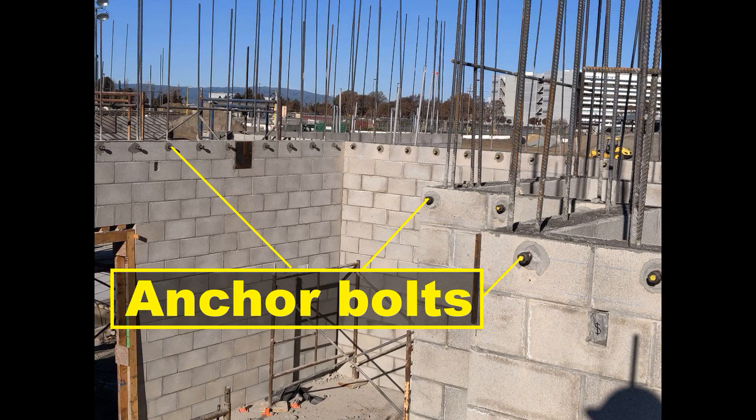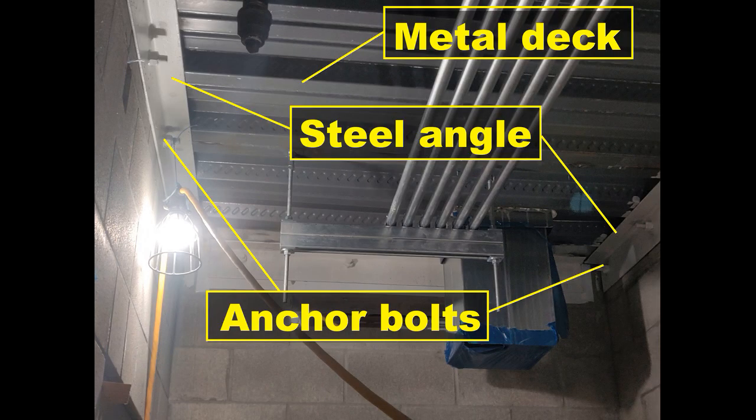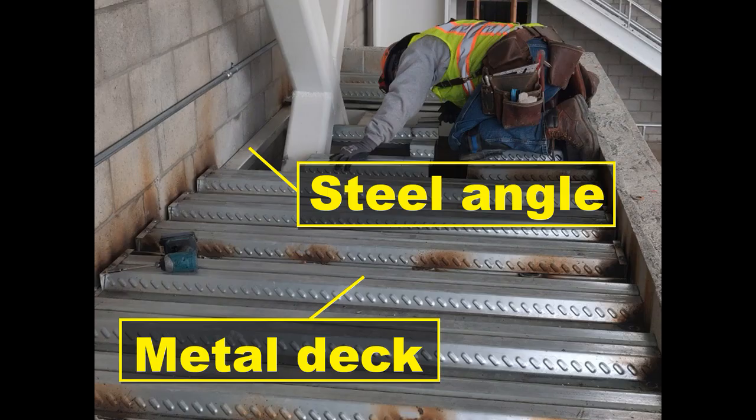The next picture shows anchors after the grout placed and consolidated and the forms have been removed and are ready for angle installation. The next step is to install a supporting angle and metal deck. Metal deck installation and inspection will be reviewed in a separate video lesson.